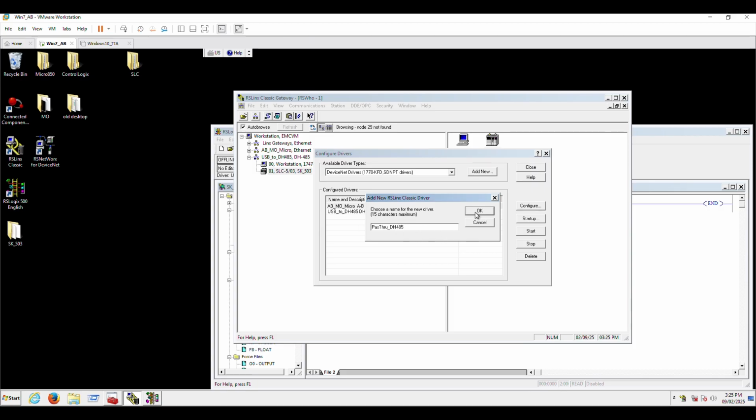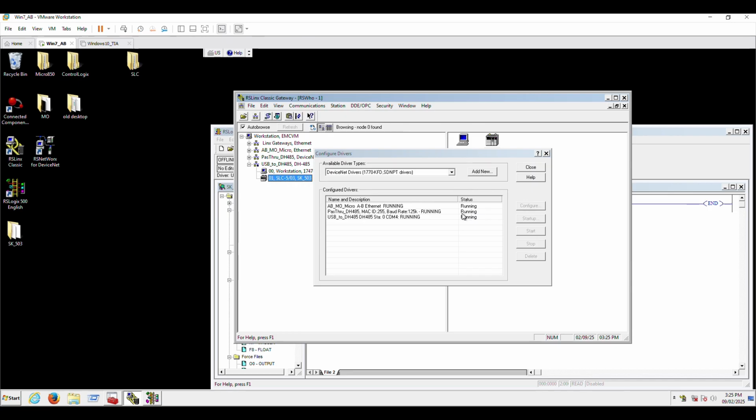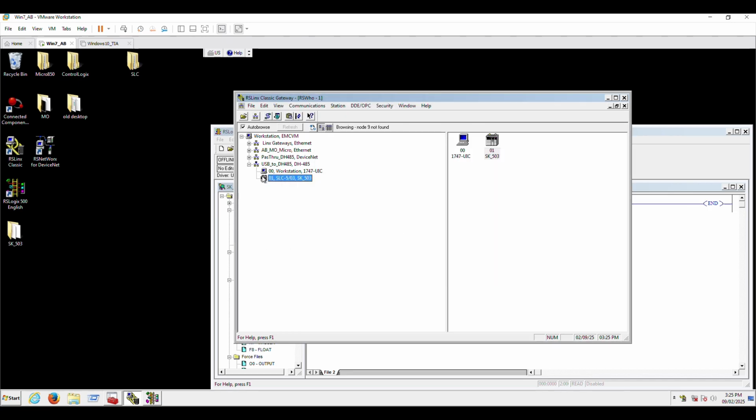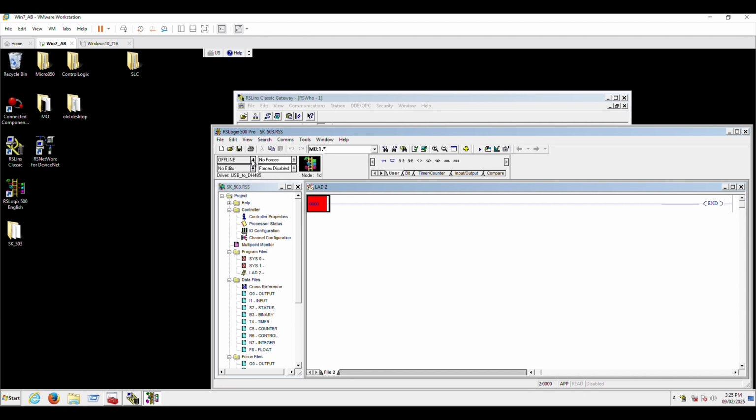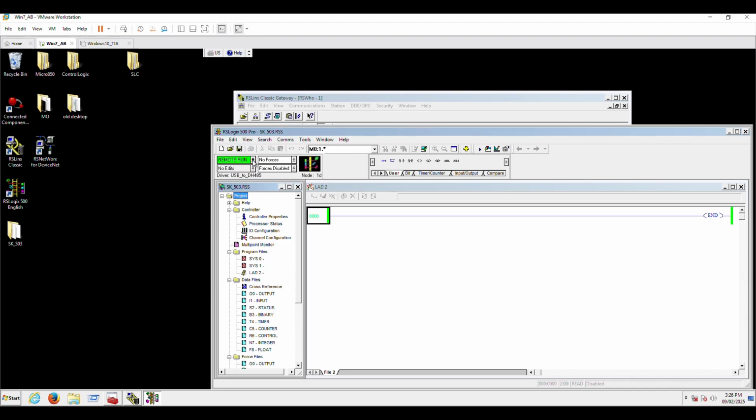One thing that I validated is the manual talks about using DH+ and Ethernet. However, I use DH485, which is significantly slower. If you grab the manual, it's the same steps, except I am further showing that, yep, you can do it with DH485 as well.